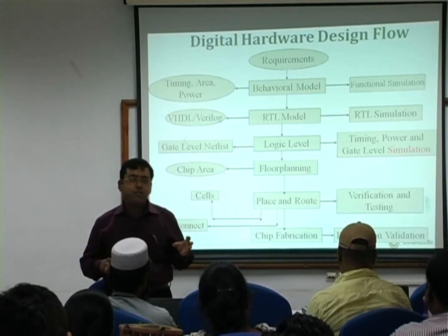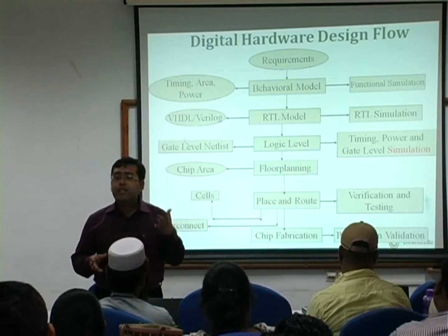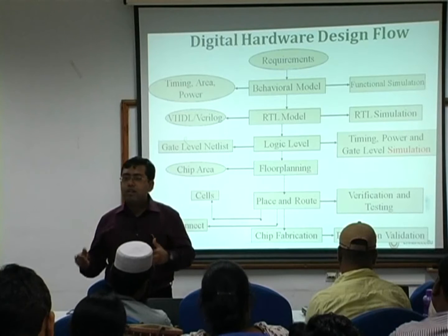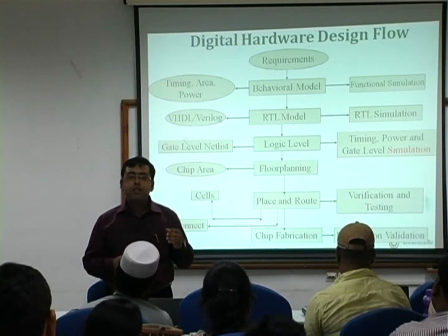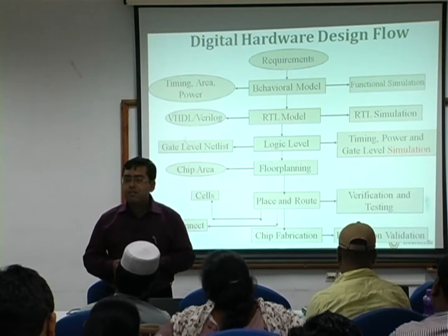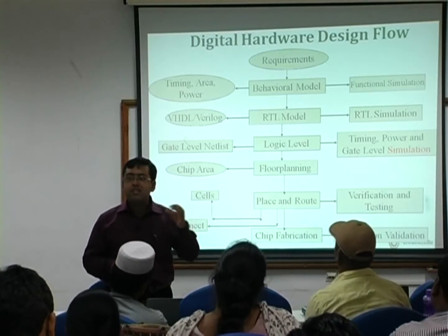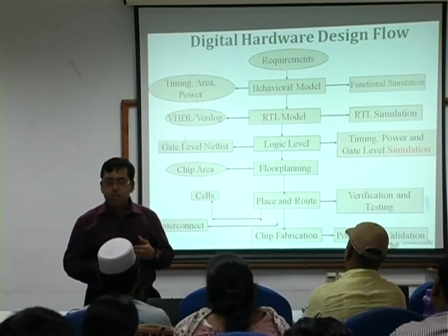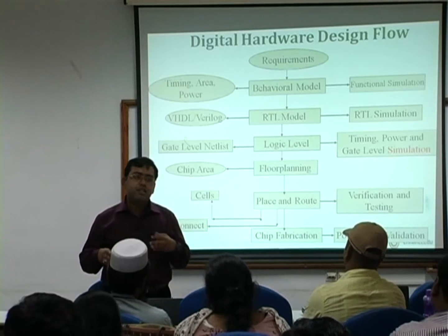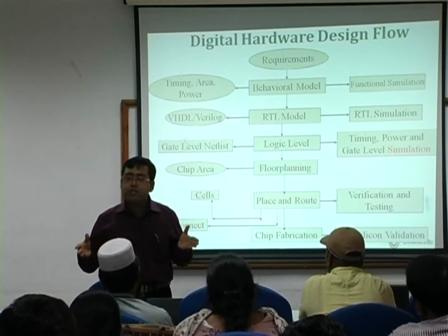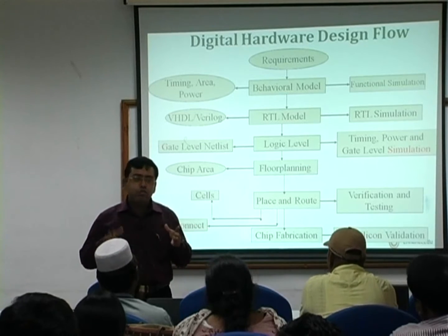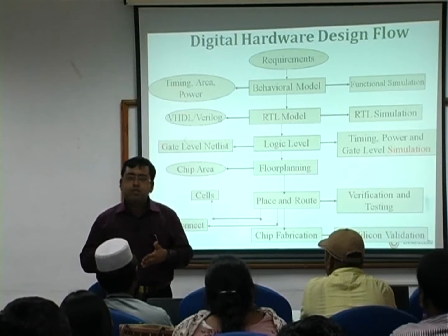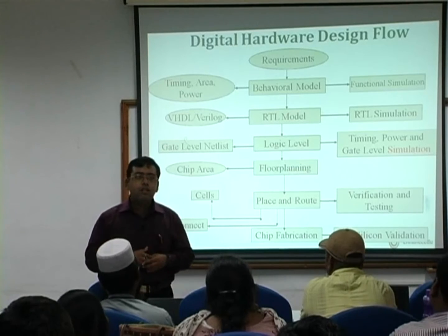Of course you won't get exactly the same set of results as you were getting in the schematic simulation, because when you were doing the schematic simulation you were not taking into account the effects of the parasitic resistances and capacitances of the interconnects, and those things are taken into consideration when you are doing the post layout simulation. But that deviation should be within a certain range, and if it is not within a certain range, then you may have to redo your layout so as to bring the departure of the post layout simulation from the schematic simulation within the tolerable limits.